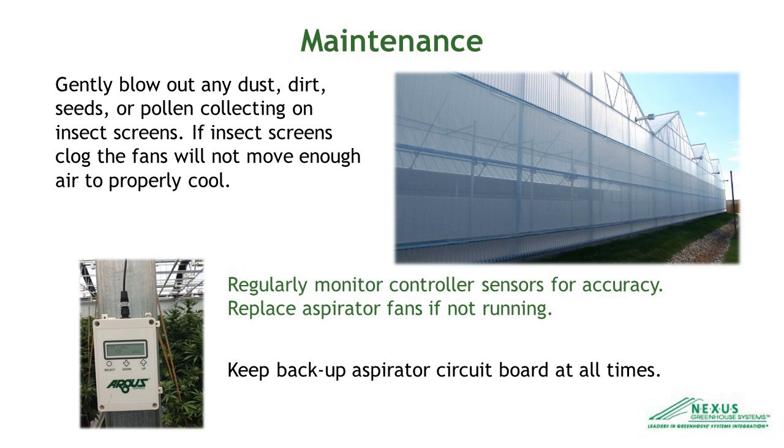People do replace them. Then regularly monitor your sensors for accuracy. So anytime you are in the greenhouse, take a look over at the aspirator, which is just another way of saying the sensor. It usually tells you the CO2 and the light levels and temperature and relative humidity. And if that piece of equipment burnt out for whatever reason, it's going to cause your controller to function improperly.